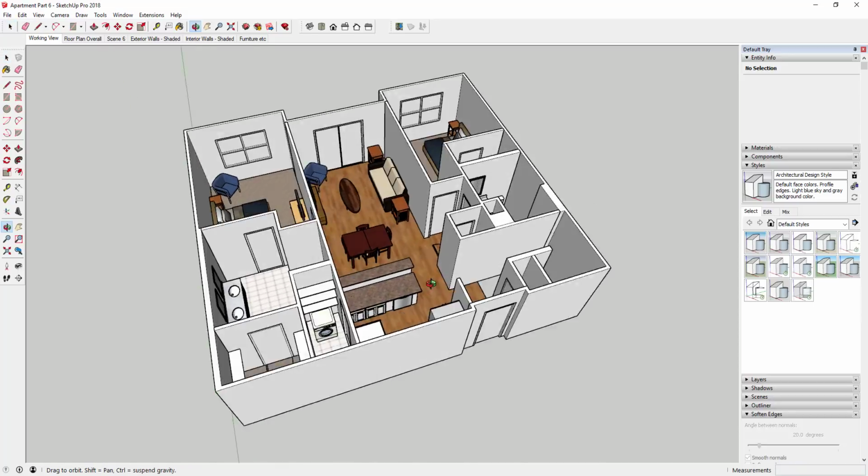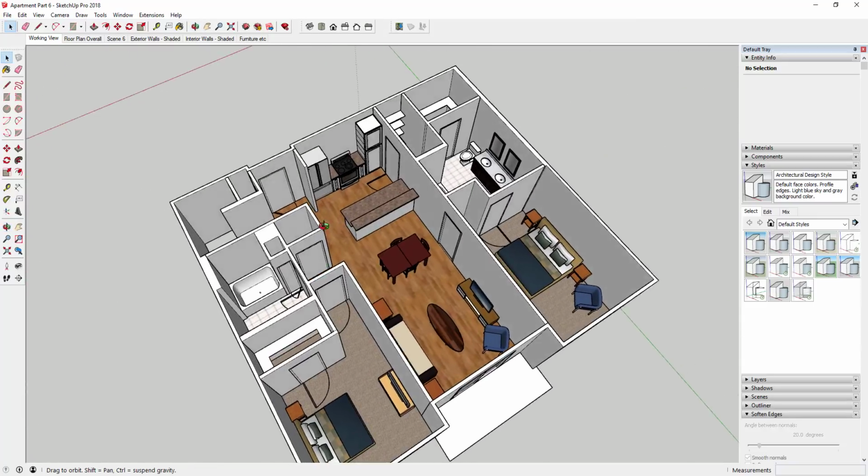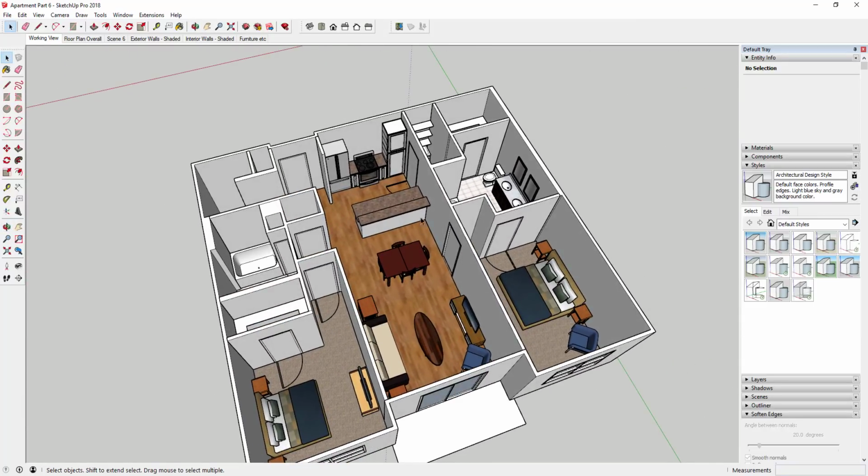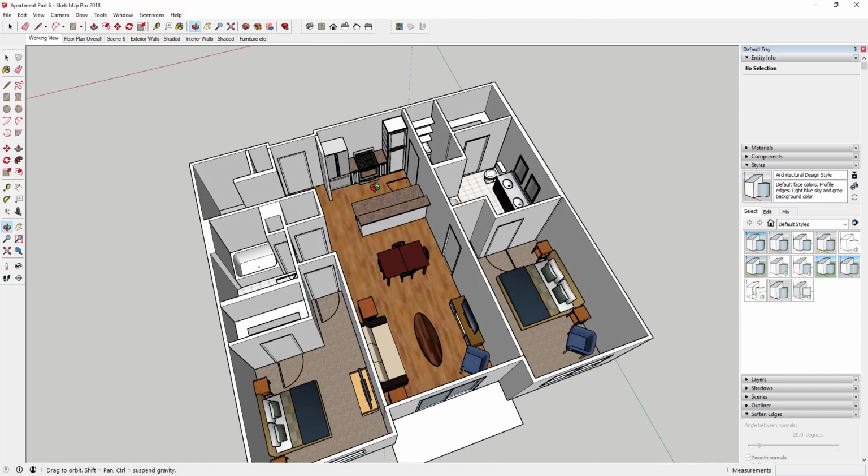And so remember, interior elevations is basically a view where you're standing inside the space looking at these objects, and so you can see them straight up and down. There's a couple different ways that you can do this. The first way is you could use a section plane in order to create your elevation view. So let's say, for example, that I wanted to create a view that showed my refrigerator, my stove, basically my kitchen looking this direction.